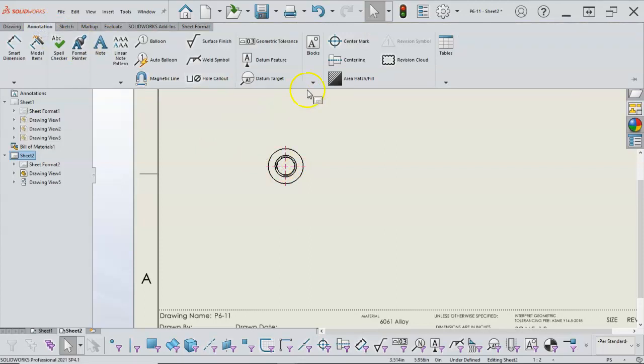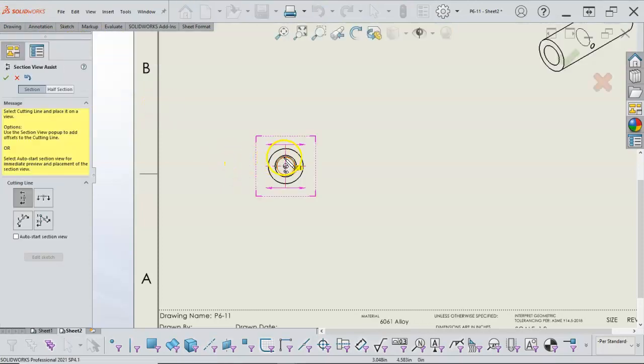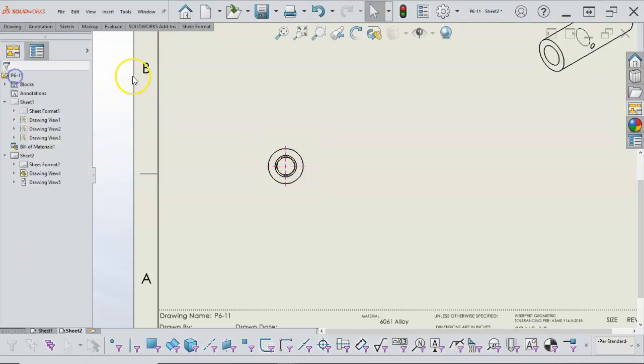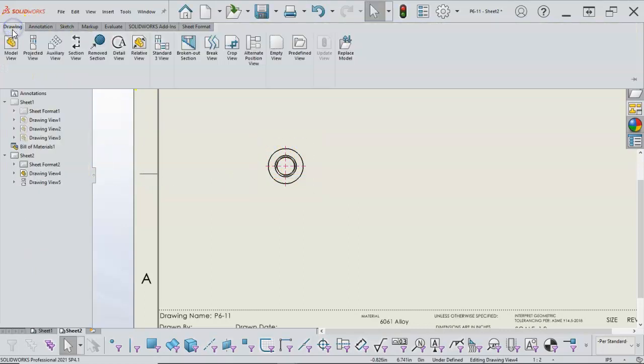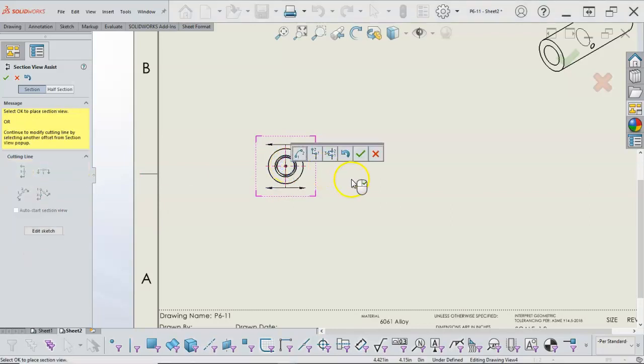become comfortable with. All right, so in the drawing, I want a section view. That section view is going to be aligned. It snaps. So let's do that again because my fingers were ahead of my mouth. Under the drawing and in the section view, we can set the direction vertical, horizontal, half sections, and then aligned, and whatever the kind of the broken, I guess notch offset, single offsets, arcs.